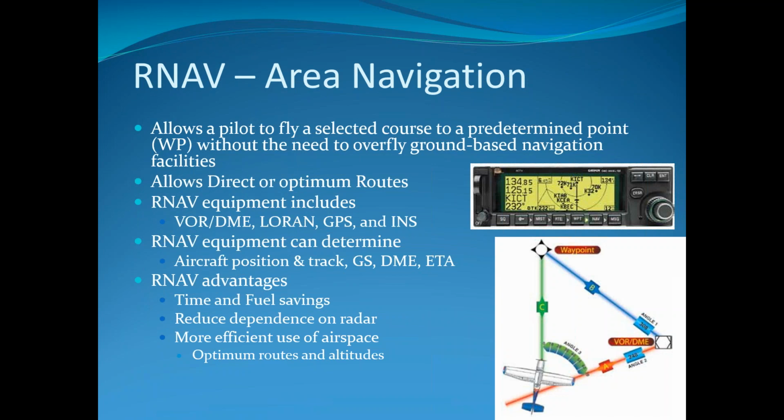And yeah, it's a lot more efficient than using these. You can think about all those VORs, looking at SkyVector and jet route, doing these zigzags that we're having to do. Well, this kind of takes a lot of that out of it because you can go direct to points that are satellite-based fixes, or intersections and waypoints, as this calls them, that aren't having to depend on having an actual VOR on the ground functioning, things like that.